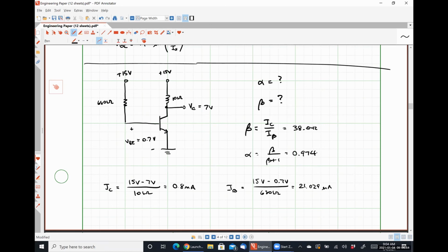I showed you guys this problem specifically because I don't want you to get intimidated by these things, because simple rules like Kirchhoff's voltage law and Ohm's law and all that stuff still totally apply to all of this stuff. This is my first time ever teaching this class at an undergraduate level, but that's where I saw most of the graduate students that I taught this stuff to a couple of years back suffered, was that they get so bogged down in all these pesky equations for how these things work, they'd forget that KVL and KCL and things like that have to also work all the time too, because they represent the fundamental laws of physics in the circuit realm, right? Kirchhoff's voltage law is the law of conservation of energy. Kirchhoff's current law is the law of conservation of charge. Those things have to be maintained at all times.